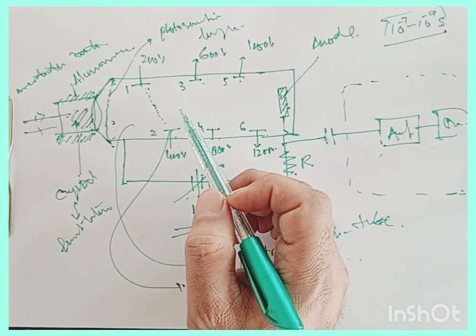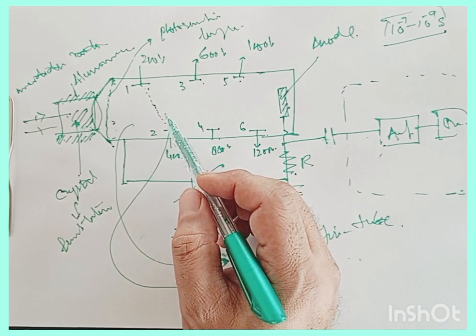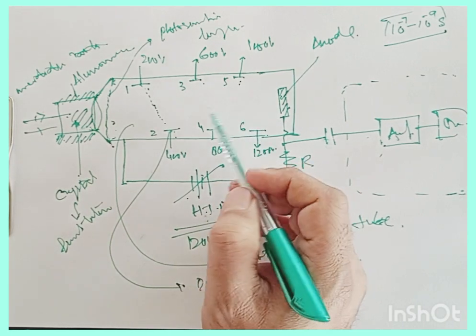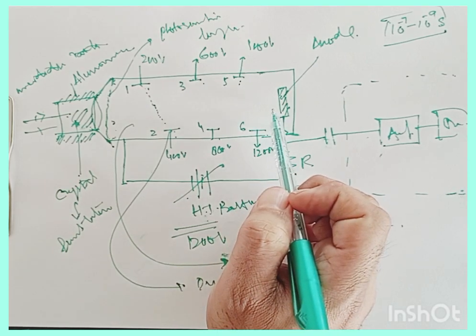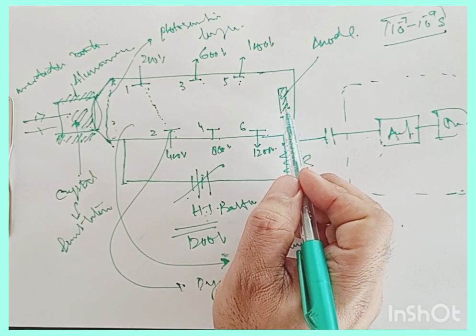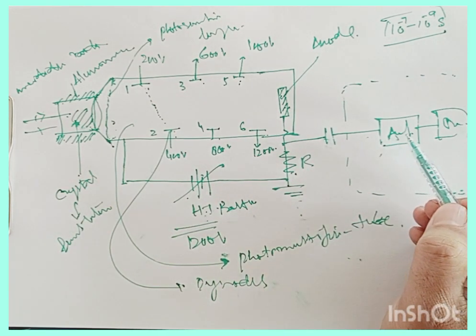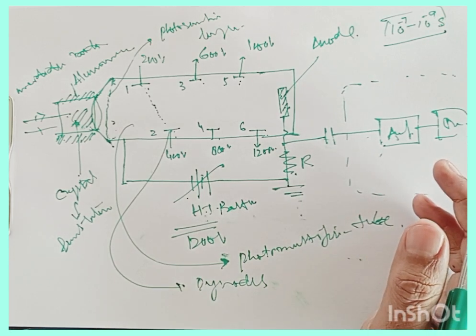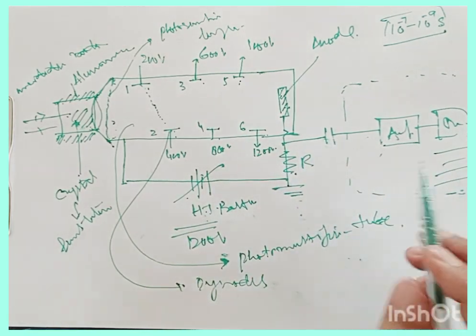So what's going on here is that these electrons are pulled towards these dynodes in successive stages, where the electrons are getting multiplied at every step due to secondary emissions. And finally, a highly amplified electrical pulse is delivered at this anode, from where this electrical pulse is amplified, and after discrimination from the noise level pulses that may be present in the signal, it is given to the recording scalers and counters that exist inside this